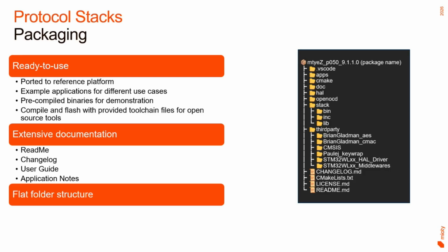And now, what does this mean for your design? Our stack is typically designed for single chip architectures, meaning you can run both the stack and your application on the same MCU. However, if your application is very resource intensive or requires strict isolation, running the mioty stack on a dedicated MCU is also possible. The stack usually runs on bare metal, but it can also be combined with an RTOS, such as FreeRTOS or TI RTOS, if your application requires multitasking.